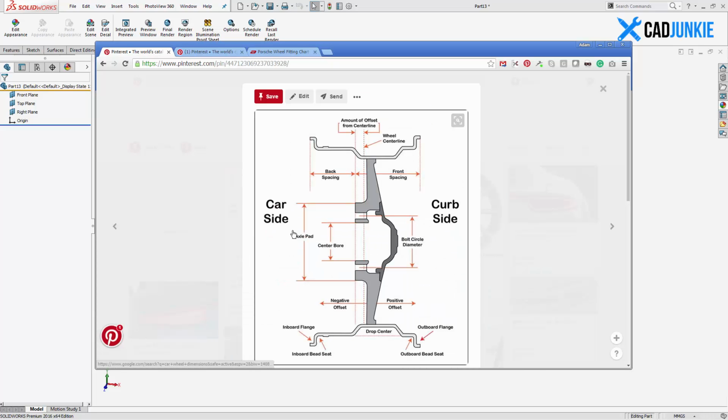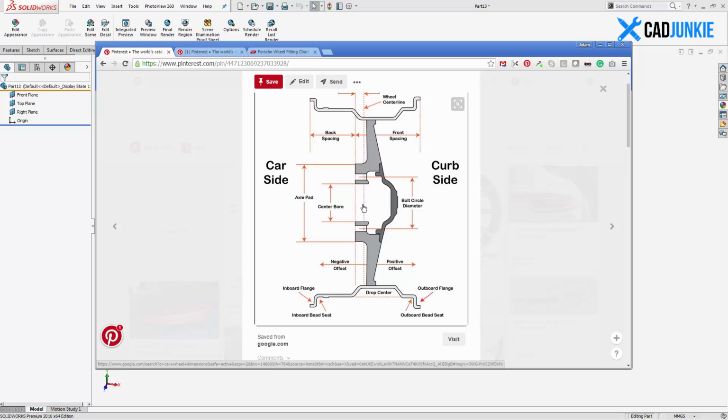If I, however, look at a more technical diagram of a wheel, I might choose that I want the origin to be right here at the center of the mounting plate where the wheel mounts up against the axle. That makes a lot more sense from a mechanical point of view. It would be right here at the middle of the center bore on the back side of the rim, and that gives us a nice flat face. There are a lot of reasons why that's a good place to be. So what we'll do is consider our right plane to be this plane, that mounting plane where the wheel meets the axle, and then we will offset a plane for the front spacing. That'll give us that number, and then we'll offset a plane to the back, and then grab one center plane to grab the center line of the wheel itself.